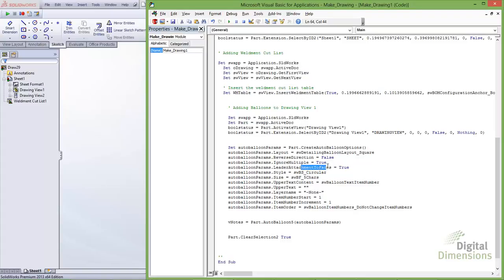Right? Any setting you'd want to set for a balloon, really the same settings you'd get when you manually insert a balloon, are here, including this 5 characters. I'm going to change that to 1 character. I don't need that much space around the balloon, or around the text rather. Any other values I wanted to set, I could. But that's pretty much it for this particular example.